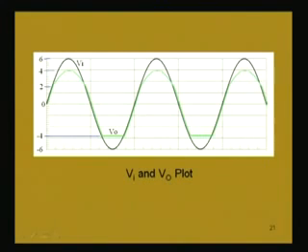such a waveform. This is also clipped, but the difference between the earlier one and this one is that here we are not having a constant voltage drop, but there is a slope. So, this waveform is similar to a sinusoidal waveform, but in the lower portion we are getting a constant clipping. This is a difference from the earlier circuits that we considered. So, the Vi and Vo plot will be like this.